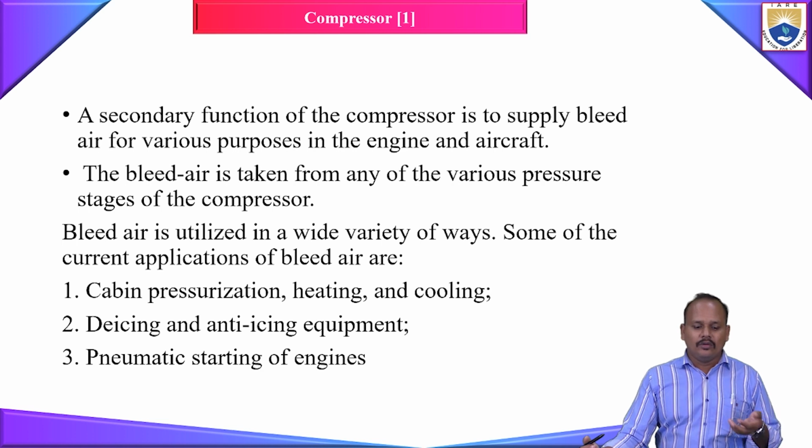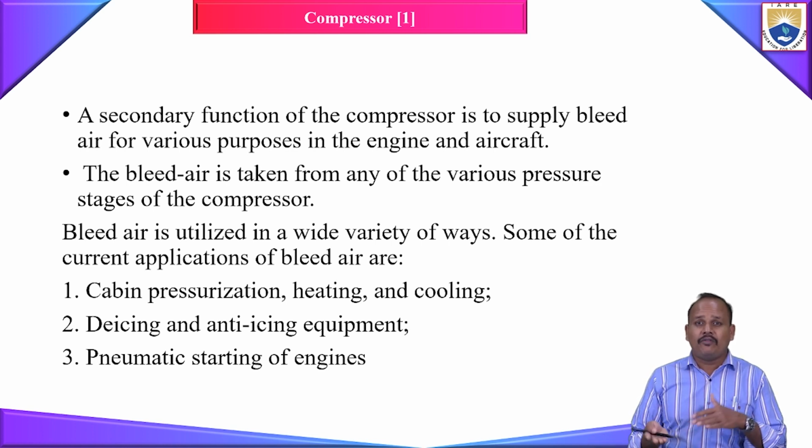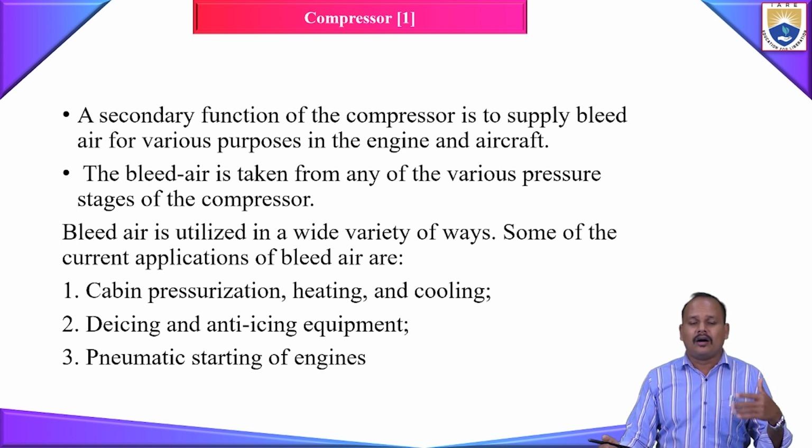So for that, what will we do? We will send high pressure air from your compressor. Basically, it will also have a bit higher temperature than your surrounding atmospheric air, which we will use for that purpose. Another one is anti-icing equipment. Anti-icing equipment basically prevents the formation of ice itself. How do we use that? Once again, by continuously blowing hot air from your compressor, we will be able to prevent the formation of ice.